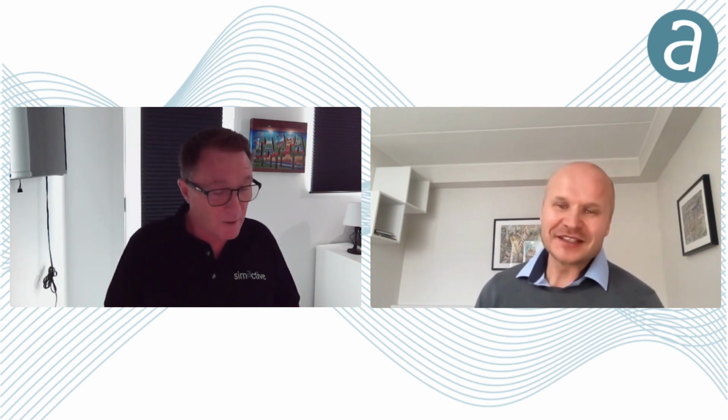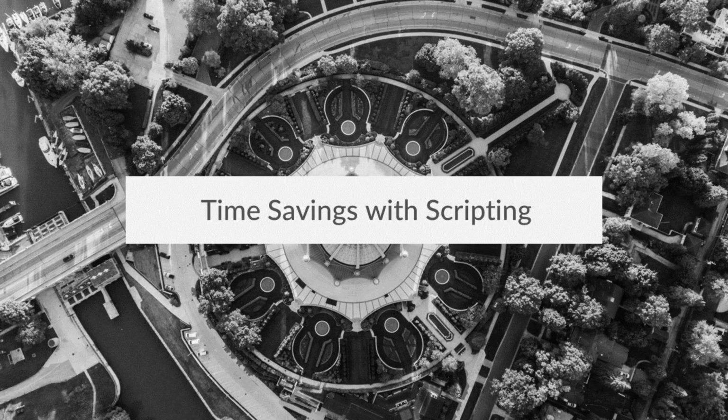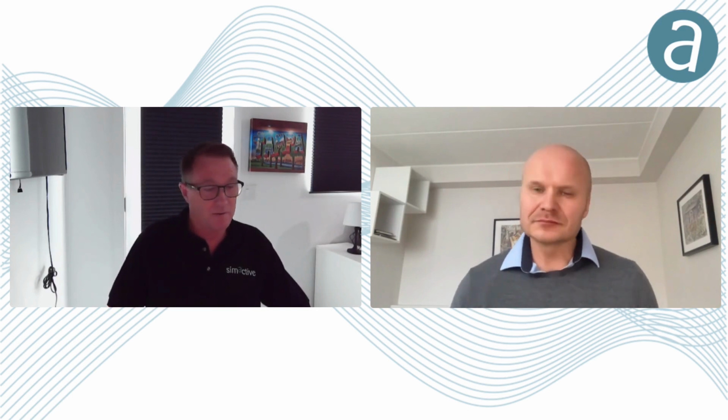And the last thing I wanted to talk about a little bit was, as you mentioned, once you have an area ready to process, your surface has already been created through the LiDAR. You've pulled all of the angular information from the trajectories that were used with the IMU and the LiDAR and sequenced those to the images. So now the AT process goes pretty fast. You're using Phase One cameras, which have a lot of dynamic range, so you have quite a bit of correction capability in the mosaic step. But from one area to the other, the steps are the same.